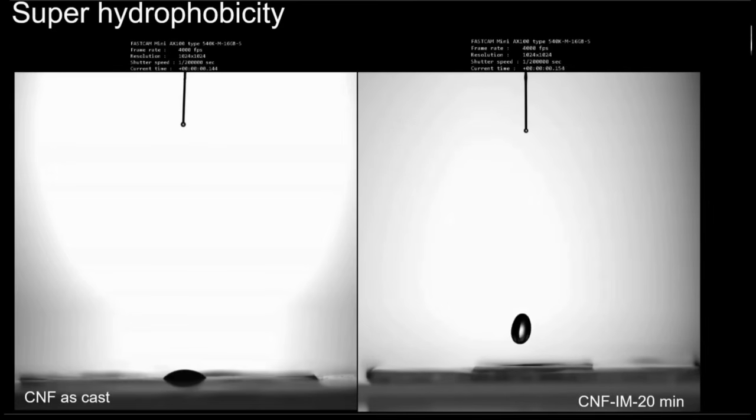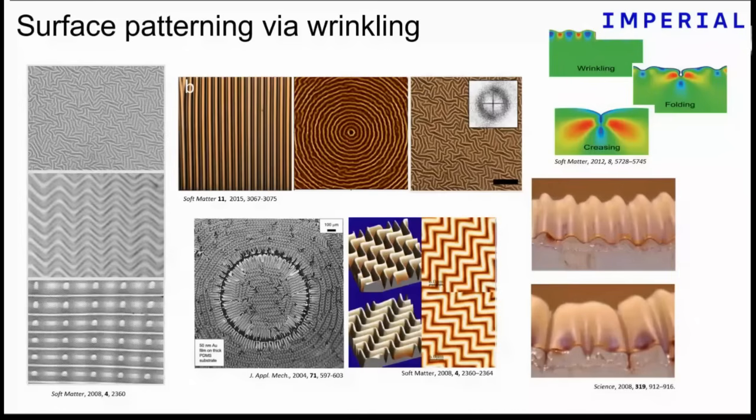So this is what happens when you take the normal cellulose that hasn't undergone this treatment, and this is what you have on the right side with the treated cellulose. So the droplets do what we wanted them to do. They bounce right off. This is about the dimension of a respiratory droplet. In this case, it's water, but we tried to load it up with proteins, with polymers, etc. They bounce right off, and once they stay, because they need to end up somewhere, right? They could roll onto the floor or whatever, but they will stay with a spectacularly large contact angle. So they will be very easily removed.